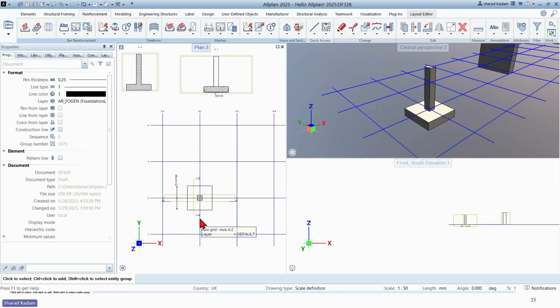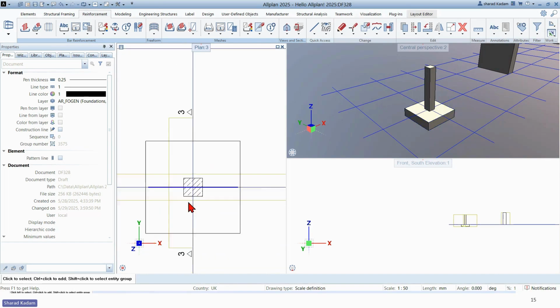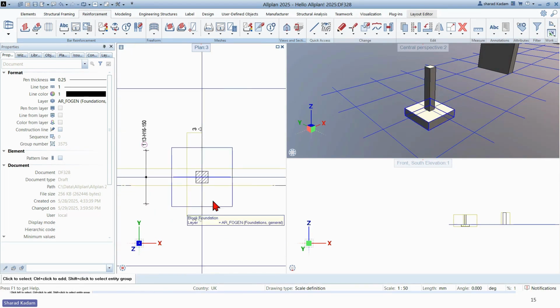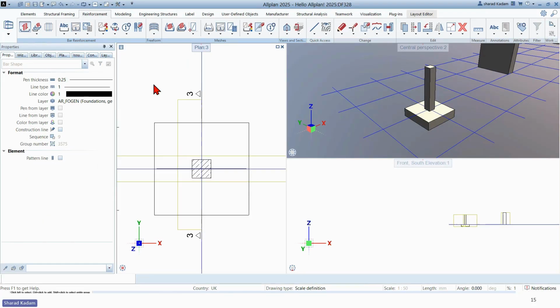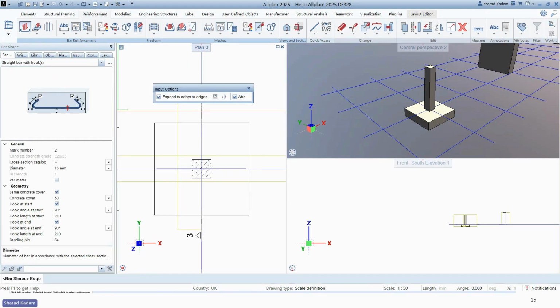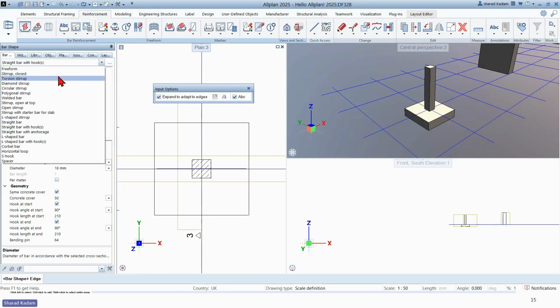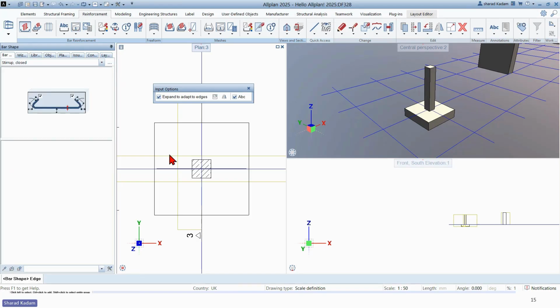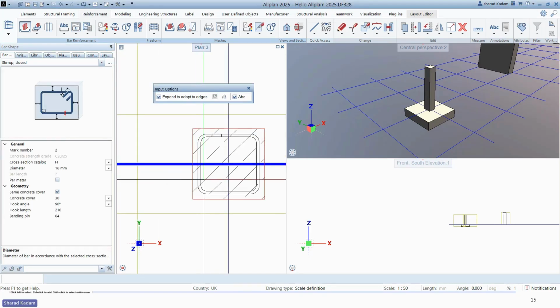The tools are real simple and real quick and fast. So I'll just repeat the same thing once again. So here we have rebars, we can choose the kind of rebar that is needed. Again, we have a drop down as well. So I'm just choosing, let's say I need to do some column rebar.